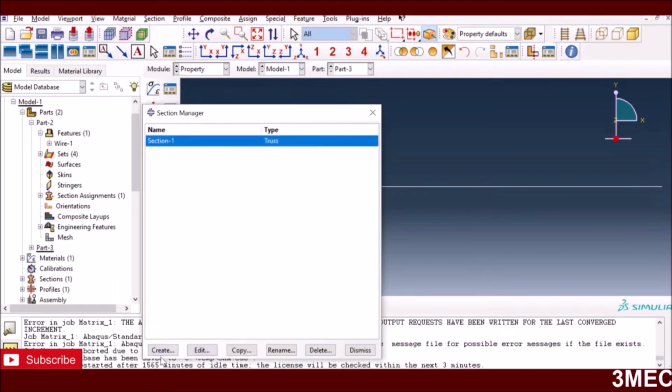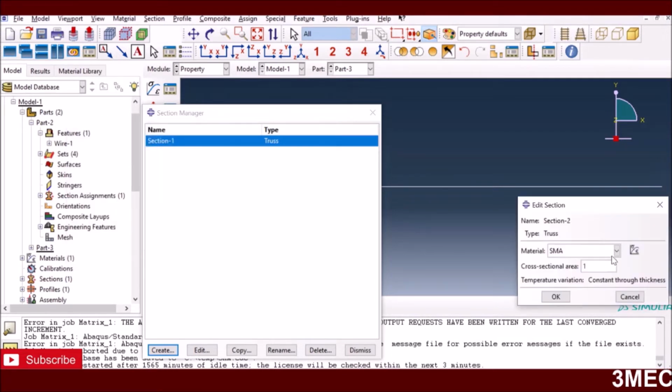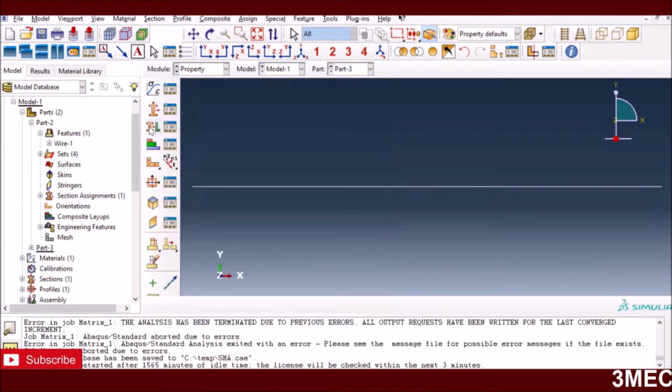Then what you do is you create a section, you create a beam section. In this case I'm using a truss element, so I create a truss section. When I press continue, I select this material and press OK. You can also give the cross section, and in this case I have already defined it, so I'm not going to create another one here. Then I assign this to this part. So this is how I have done it here.